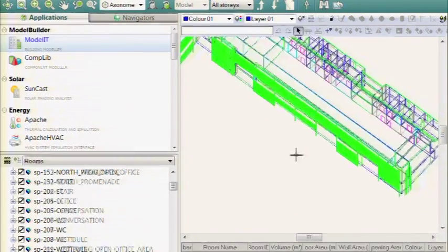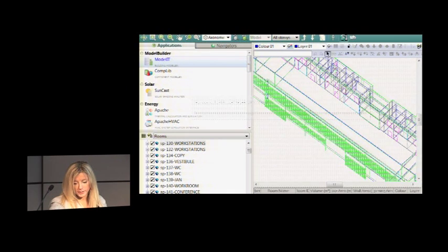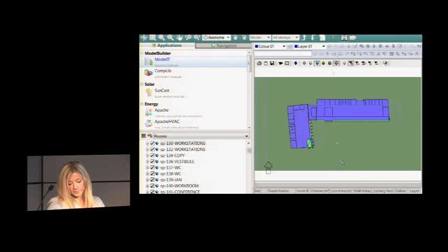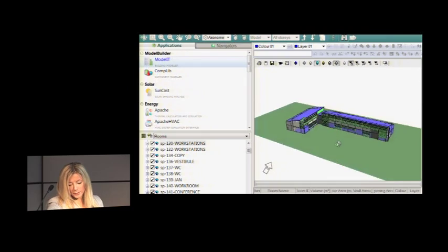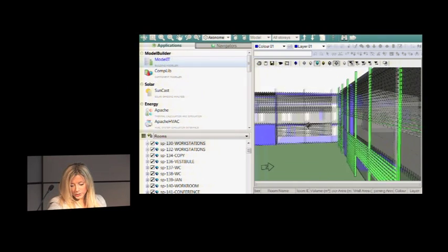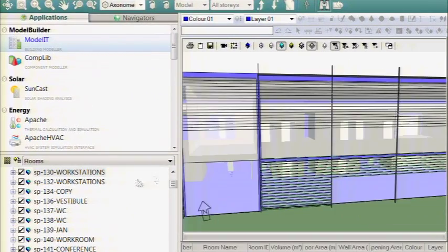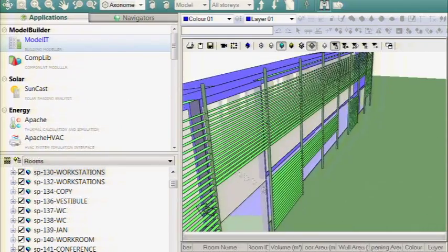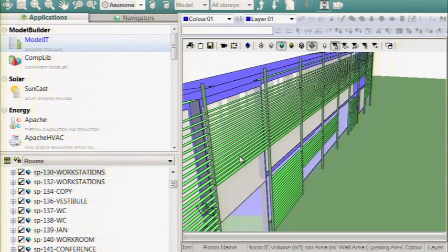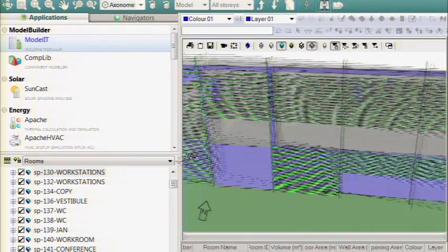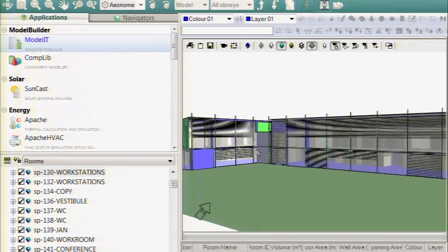Okay, so now this is a model that we did import. Let's see if it will come up. But cleaned it up in a little bit of a different way. So you can see that what I did here is these planes, I did them as one surface. I made sure when I was creating this facade to not do some sort of 6-sided object with a lot of detail, and I created this so that it would be simple enough and not add as many shading surfaces to it.